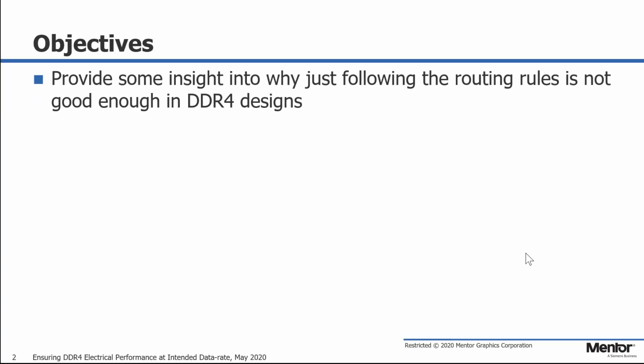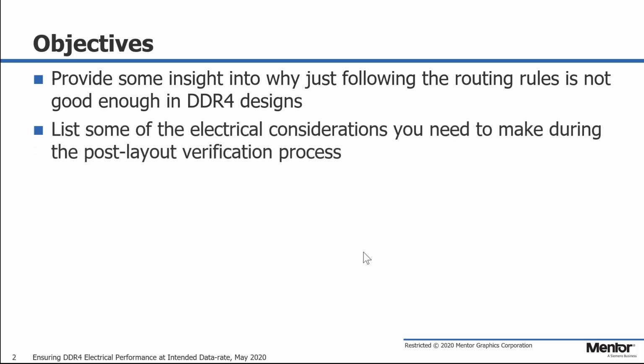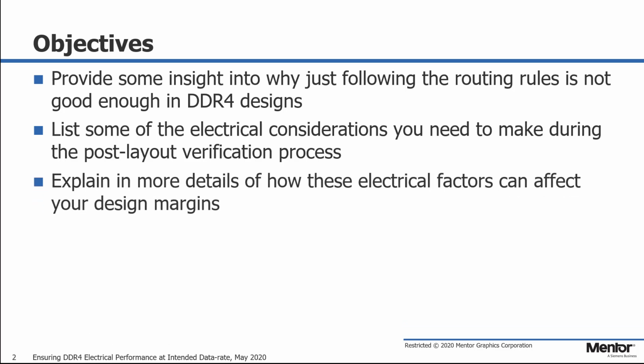First, I'll provide some insight into why just following the routing rules provided by either the controller or memory vendor is not good enough in DDR4 designs nowadays running at high data rates. Secondly, I will list some of the electrical considerations you need to make during the post-layout verification process. I will also explain in more detail some of these device-related electrical factors, such as why we need to consider derating and VREF training in DDR4 designs.